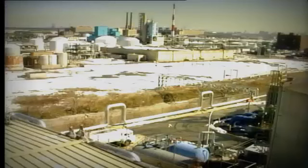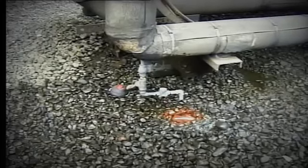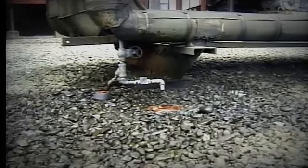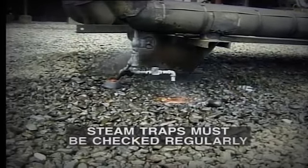In some cases, the auxiliary steam piping has to travel considerable distances, for example, to an oil tank farm. There is a tendency for heat to be lost from the pipework even though it is insulated, and the steam temperature rapidly falls to saturation and condensation begins. For this reason, steam traps are located frequently throughout the auxiliary steam system. The operator should regularly check that the steam traps are functioning correctly, that is, to discharge condensate in regular bursts.